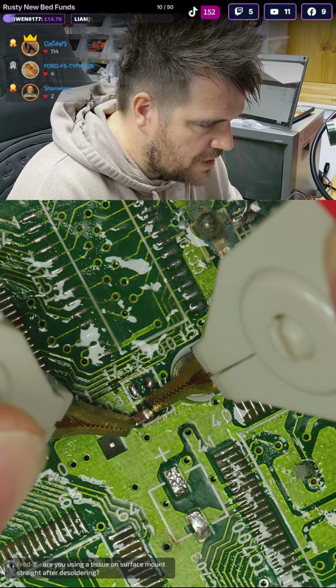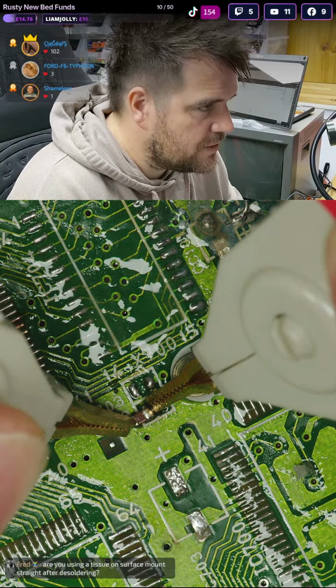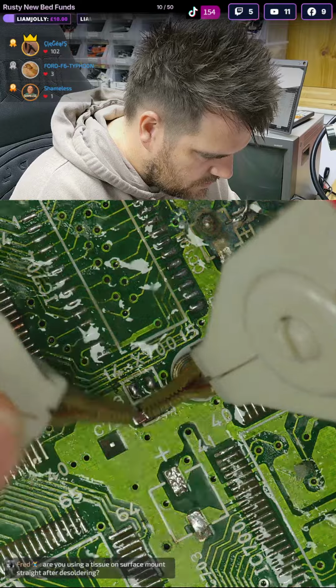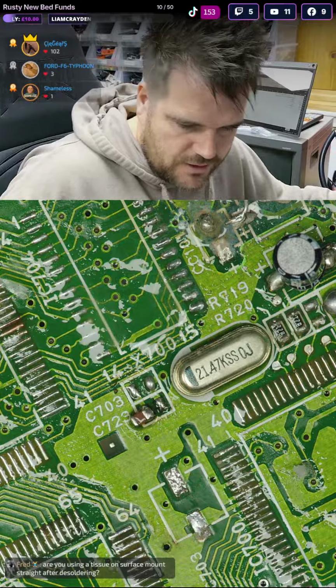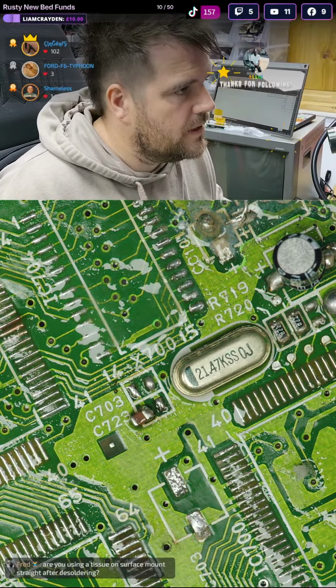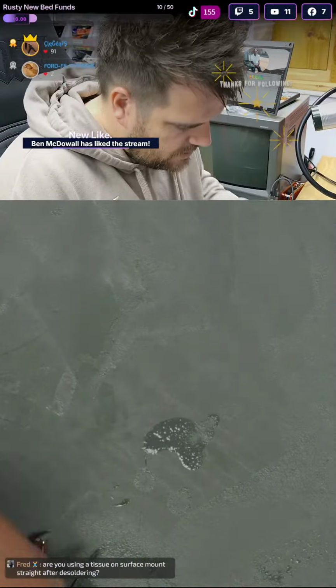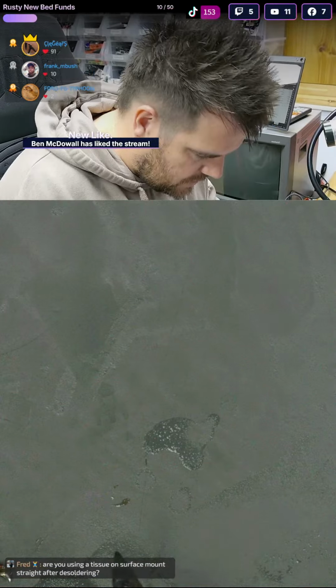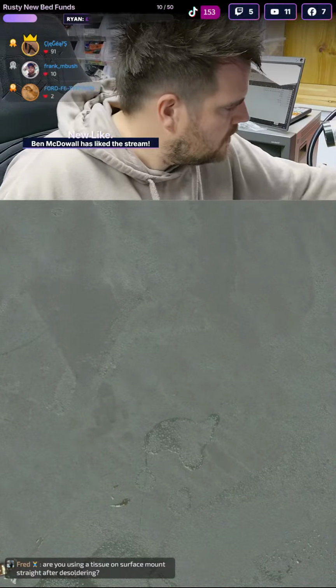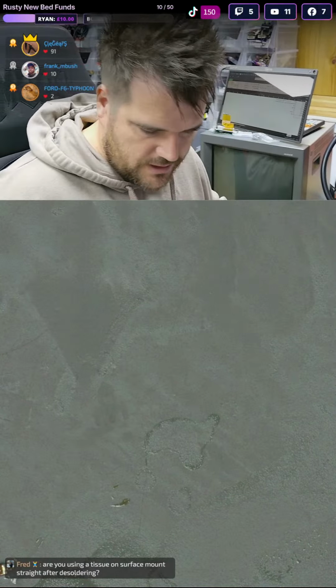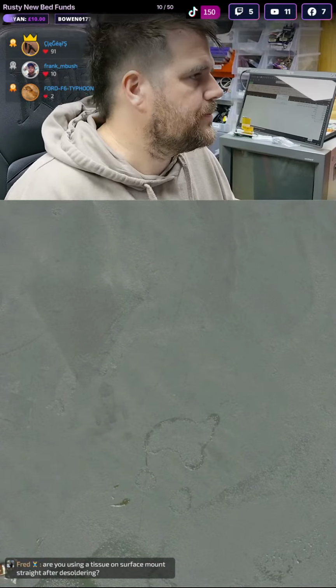That's now measuring 2 nanofarad. Actually, let's take this off the board completely, because at that lower range, leaving it on the board, we're getting a little bit of potential capacitance from the traces on the board. I don't know why I left it on. I was thinking it was a resistor for a minute.